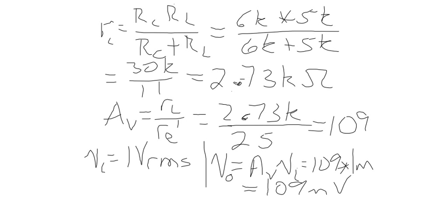So we've multiplied that voltage waveform over 100 times. And we could do more. We can stick another amplifier just like this one at the output of this one. Stack them up, so to speak. Have the output of one feed the input of the next one. We call that cascading.